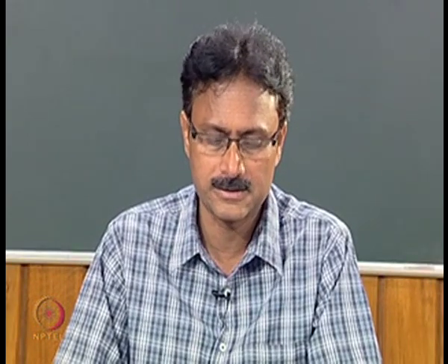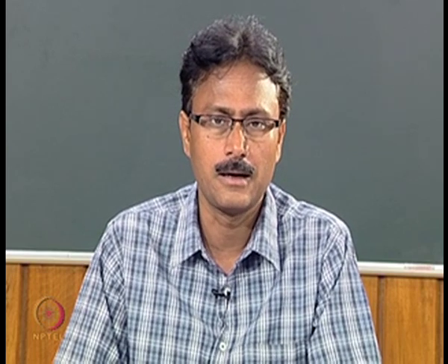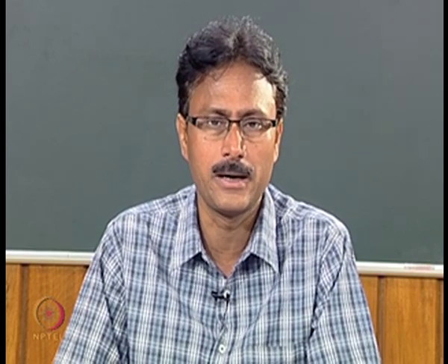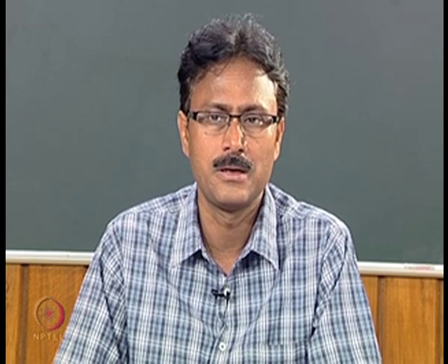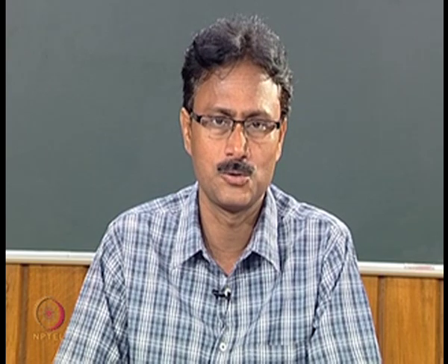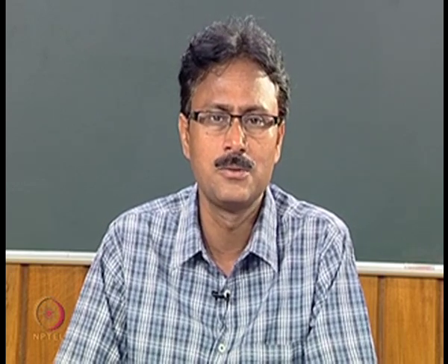Welcome to the lecture titled Identification of Second Order plus Dead Time Transfer Function Model. In our earlier lectures, we have seen how to identify simple transfer function models, where the system can have a delay and gain, or a first order dynamics and delay, and so on. Depending on the type of sustained oscillatory output signal, we decide what type of transfer function model one has to identify. Thereafter, we employ the simple formulae we have derived in our earlier lectures to find the parameters of simple transfer function models.